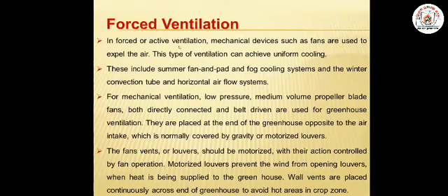In forced or active ventilation, mechanical devices such as fans are used to expel or exhaust the air. This type of ventilation can achieve uniform cooling. This includes summer fan and pad cooling and fog cooling systems, and the winter convection tube and horizontal air flow systems. For mechanical ventilation, low pressure, medium volume propeller blade fans, both directly connected and belt driven, are used for